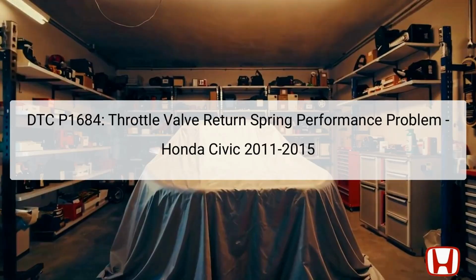The DTC P1684 indicates a performance issue with the throttle valve return spring in the Honda Civic models from 2011 to 2015. This diagnostic trouble code relates specifically to the throttle body's functionality, which is crucial for engine control. The throttle valve is a component that regulates airflow into the engine's intake, thereby affecting engine speed and performance.